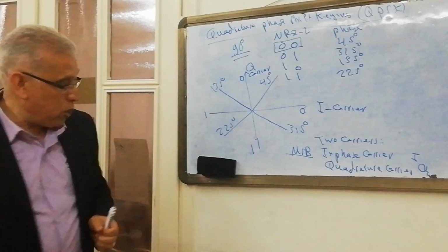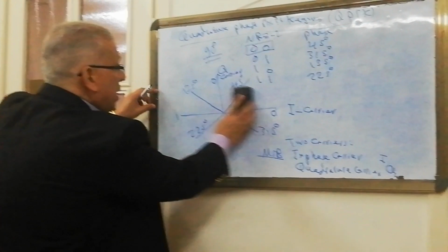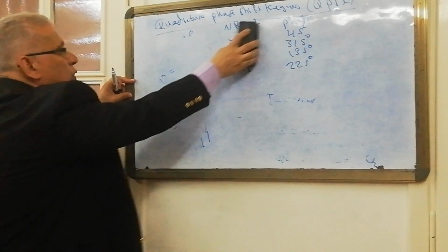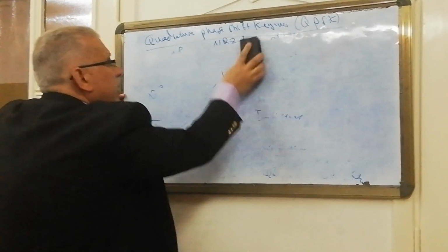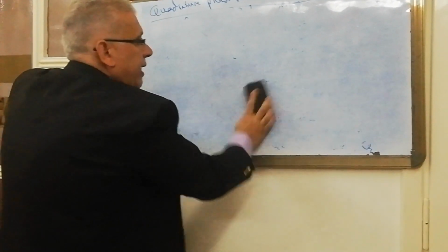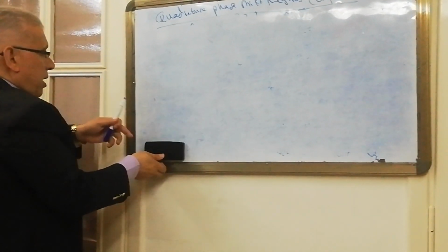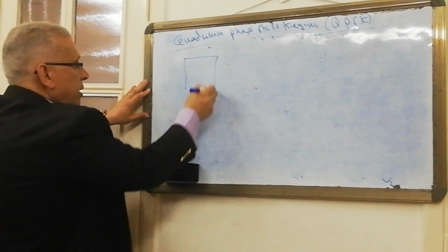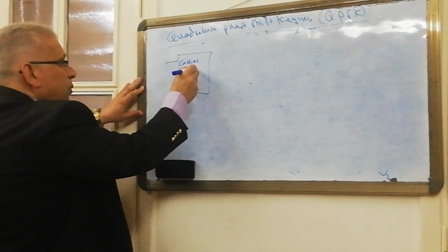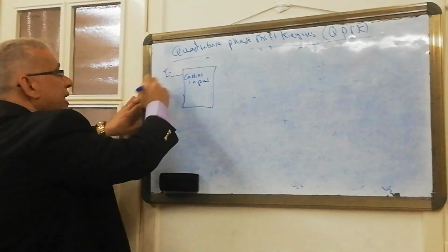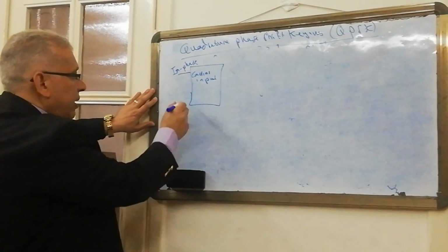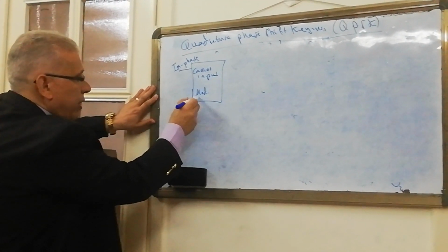Now I am going to draw the block diagram of our transmitter, or the modulator. We will have 2 modulators. The first one is the I modulator, the in-phase modulator. The second is the Q modulator. The first modulator has the carrier input, where we apply the in-phase carrier. Also we have the data input, or modulation input.